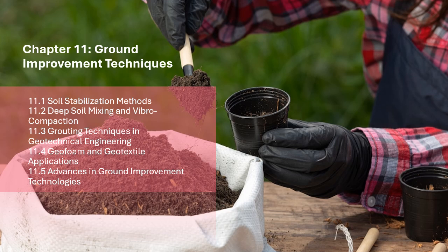The technique helps to reduce both immediate and long-term settlement of structures by densifying the soil, making it more resistant to deformation under load. Liquefaction mitigation. By densifying soils, vibrocompaction reduces the risk of liquefaction in areas subject to earthquakes, ensuring safer construction in seismic zones.